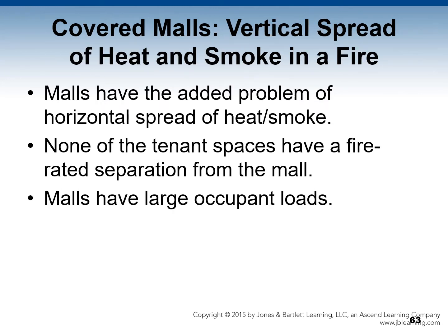With covered malls, you can have vertical spread of heat and smoke in a fire, but malls have the added problem of horizontal spread of heat and smoke. None of the tenant spaces have a fire-rated separation from the mall itself, except for large anchor stores. Malls have large occupant loads.